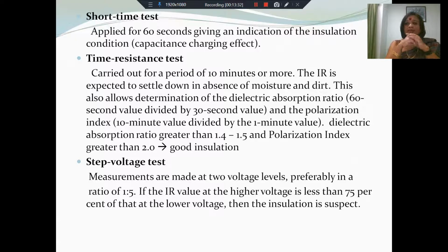If it drastically reduces, it means that it is conducting a greater proportion of current, which means that certain things must be happening which cannot be attributed to simple conduction. It may be that you have partial discharges, or some defects which are causing very high losses.